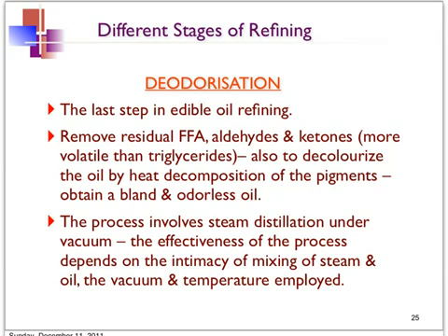So it is very important during this process to get a very intimate mixing of the steam and the oil, as well as the vacuum and the temperature. The control of these parameters is important to get an efficient deodorization to remove the free fatty acid down to a very low level, less than 0.01%.